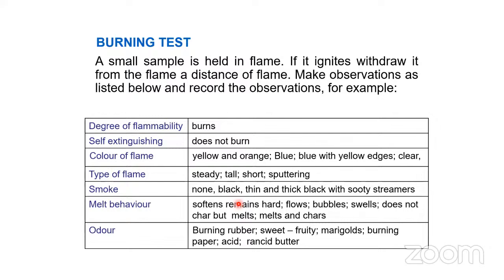So next, after that basic test, is somewhat another technique to identify the plastic material, which is nothing but the burning test, as one of you mentioned earlier. By burning the polymeric granules or polymeric material, we can identify the type of polymer.